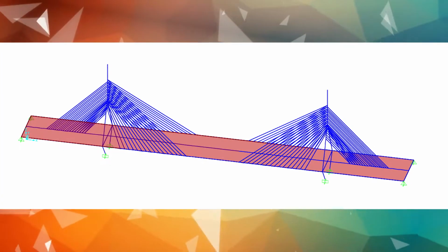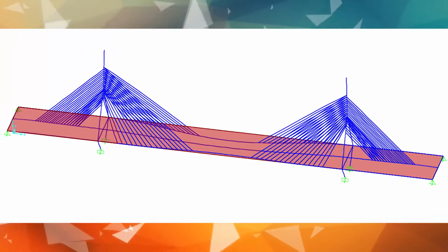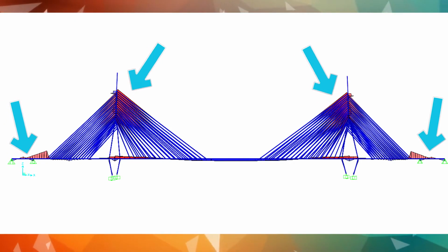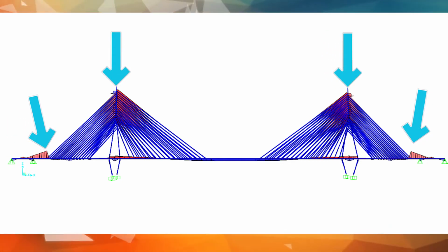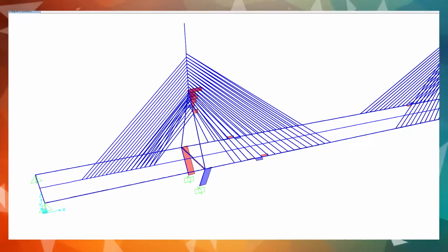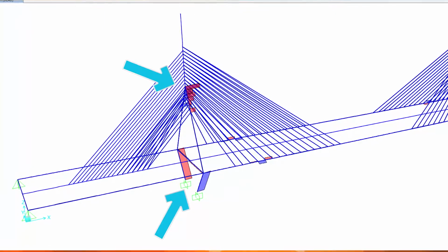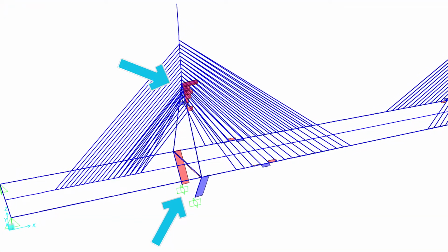To analyze the structural properties of the bridge, we created a model in SAP2000. While this deformed shape diagram is exaggerated, it shows how the bridge will deflect under a static load. The bending moment diagram shows large moments at the connections between the towers and the cables, as well as at either end of the road spans. The force diagram shows large forces in the supports and at the top of the triangular arch. The results of the analysis will not be 100% accurate due to the estimated dimensions and approximated materials.